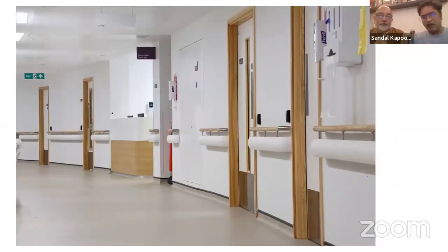Then another important point when we are doing the equipment planning, even in design, is that wall guards, bumper rails, and kick plates have to be placed. They are very important because a stretcher is moved by a person from the other end, and at the front end of the stretcher it hits the wall and it hits the door. So it's very important to have the bumpers there to prevent any scratches or damage to the doors and to the walls.